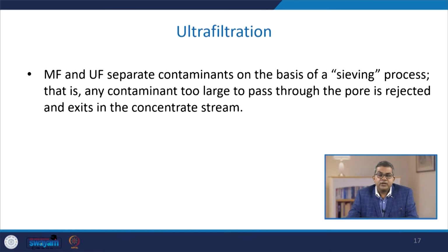Microfiltration and ultrafiltration separate contaminants on the basis of a sieving process, that is, any contaminant too large to pass through the pore is rejected and exists in the concentrate stream, which we showed in the earlier photograph.